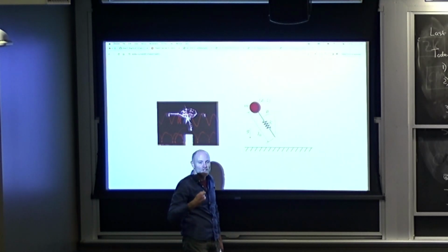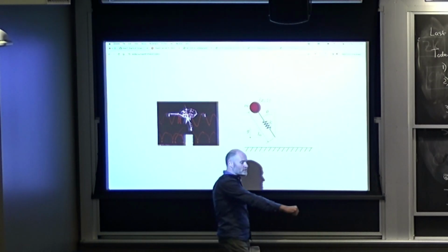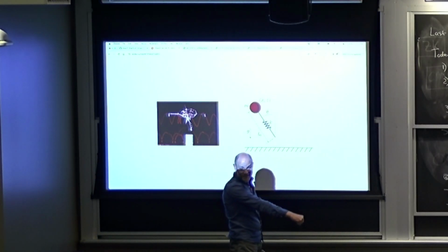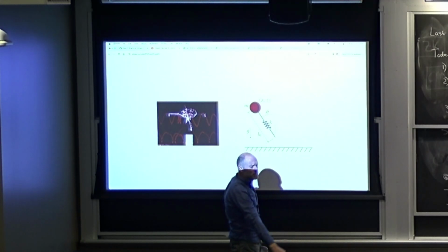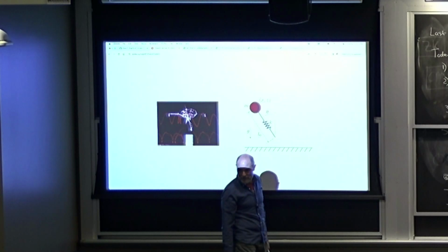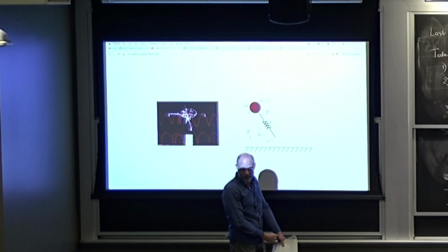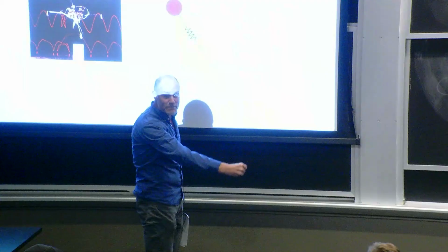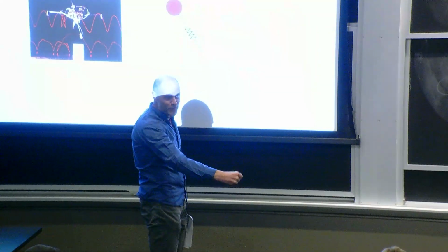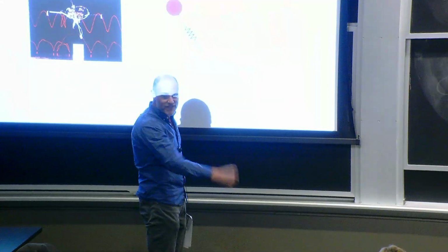That means you don't have to know where the terrain is. It turns out, if you're just hopping along, and you just pretend that I'm going to hit the terrain at a certain time all the time, and you just close your eyes and sweep your leg through this schedule, then whenever you happen to hit the ground, you're going to be in the right place. Okay? So there's a blind, open loop, deadbeat controller for the SLIP model that doesn't have to know anything about the terrain.